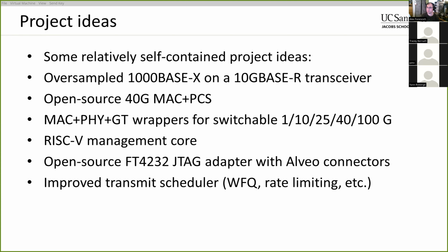So if we have a RISC-V core or a VexRiscv with the debug extensions, I'm presuming that you can use those to basically erase and update the firmware. Obviously that wouldn't be persistent, but you could definitely use that for debugging. Load a new firmware, check to see if it works, and if it looks good, then integrate it into the bit file build process for the FPGA. That would allow you to very easily test out new functionality.